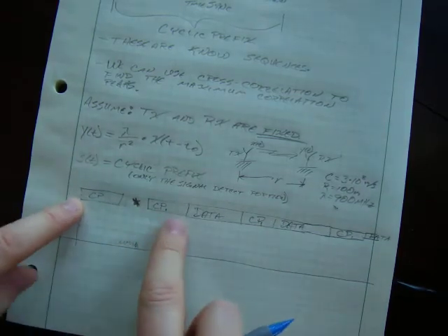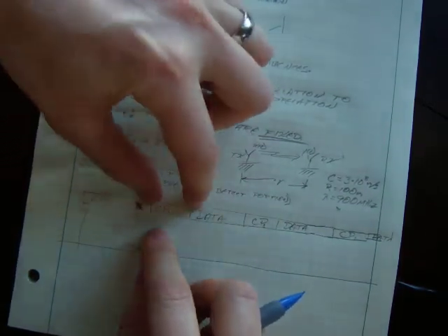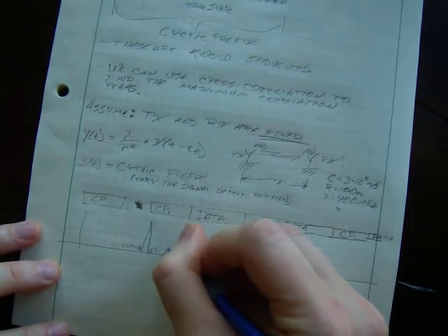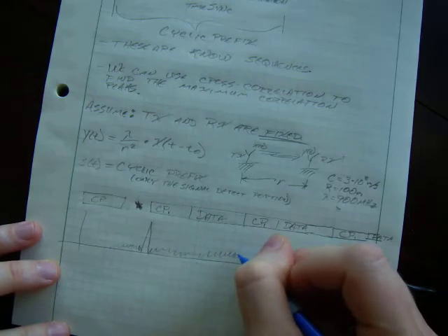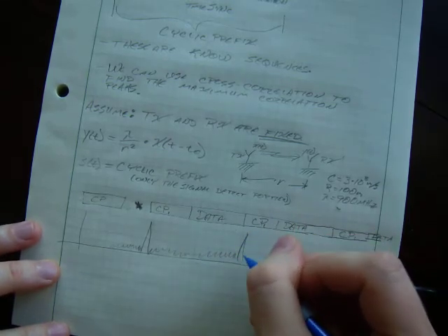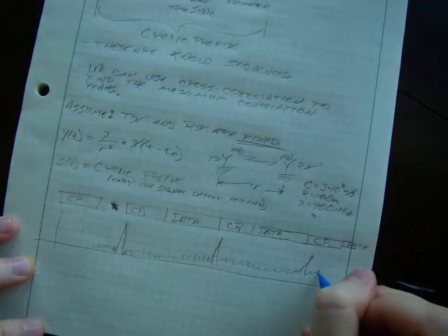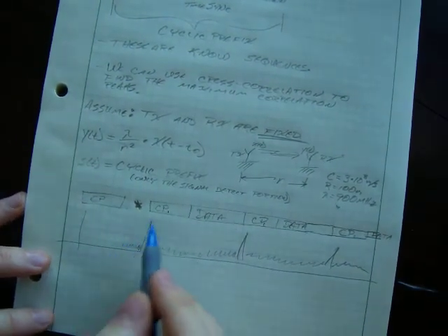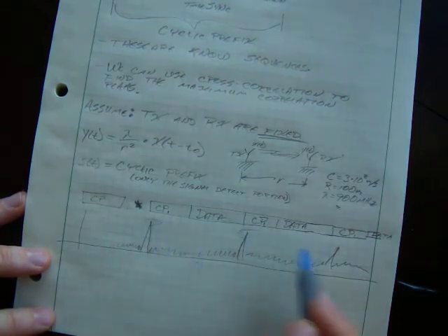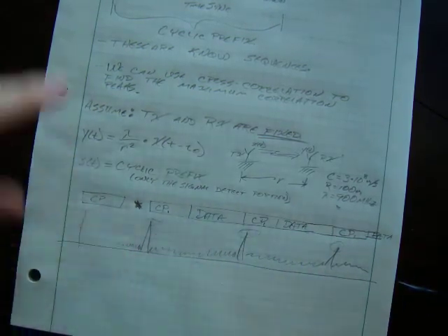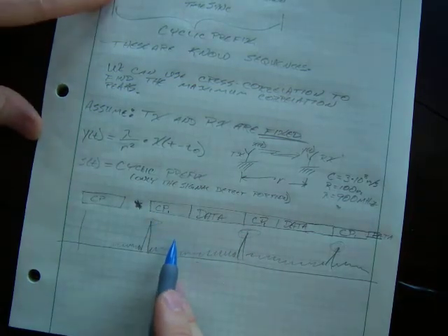But then when these two overlap, we're going to have a spike in the correlation. And then it's going to continue on, and at the next one, it's going to have another spike. Then it's going to carry on, and then it's going to have another spike and carry on. So this is what we're looking for. There should be this pulse train where we've got all these spikes emerging from it. And in a real system, this is where the automatic gain control comes into play.